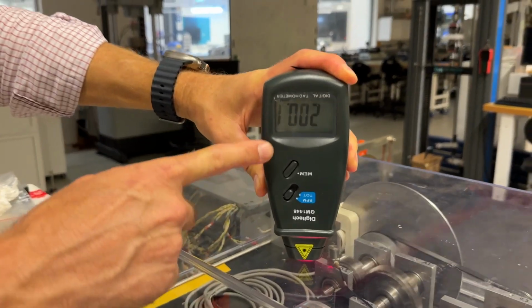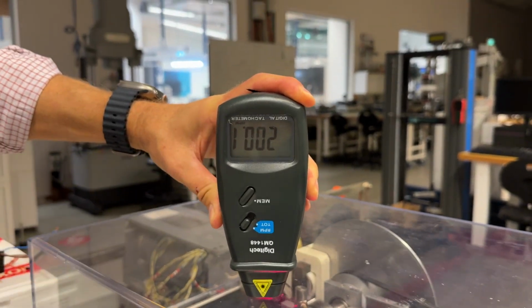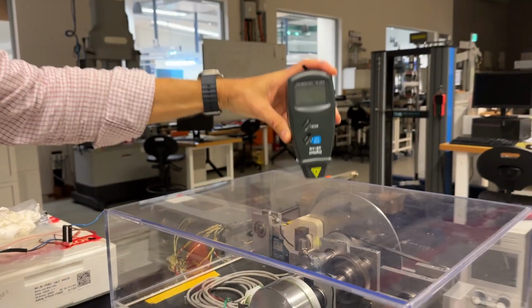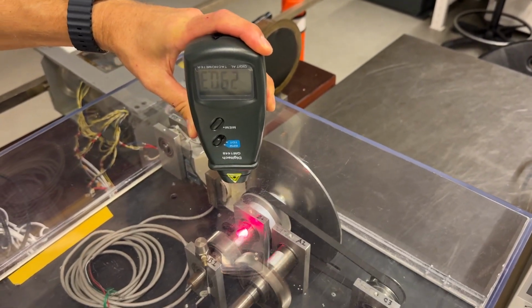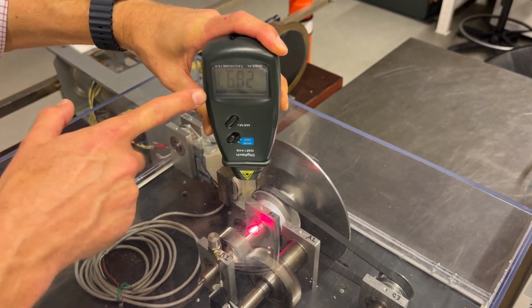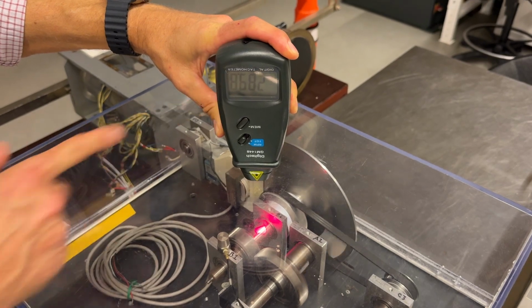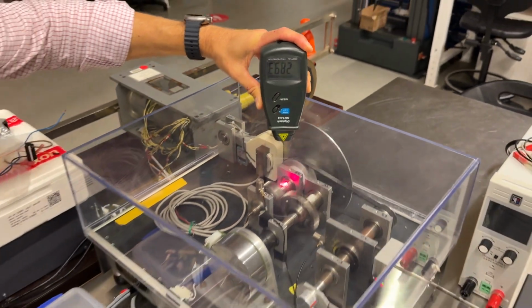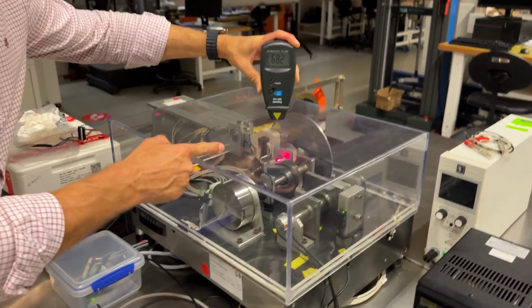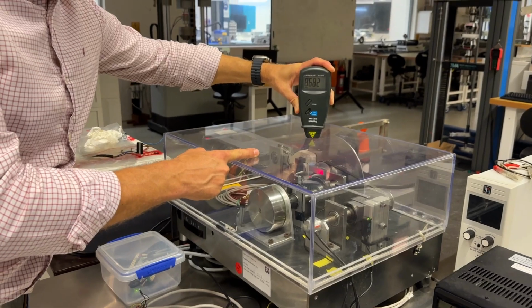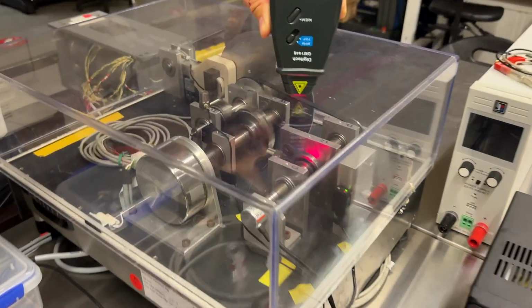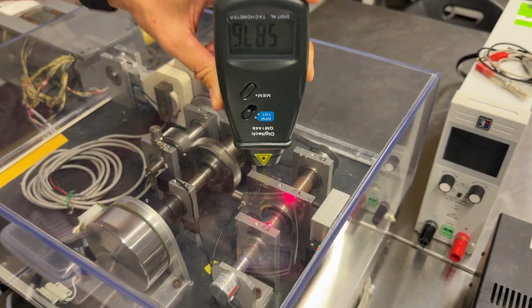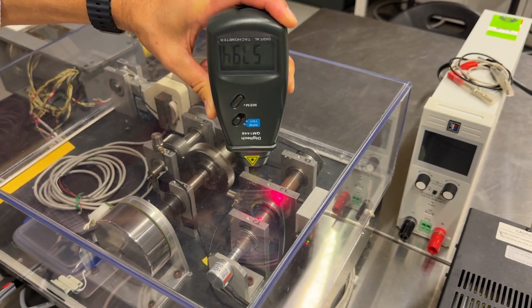It's upside down, unfortunately, but it's 200 RPM for this shaft. I've got another piece of tape over here, so this is our 29 to 20, so that's 290 RPM, 1.45 times the shaft speed here, and then this shaft over here is rotating at 2.9 times the shaft speed, so 580 RPM.